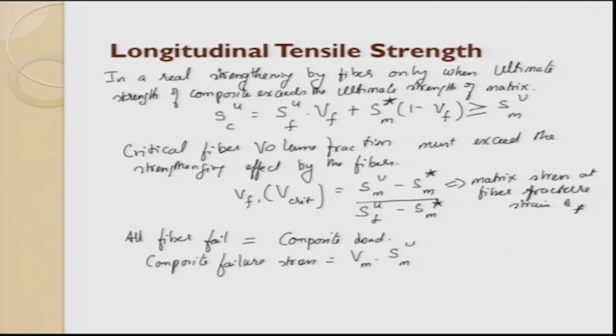So what happens is, if you see the strength versus volume fraction, there is something like a graph like this. So you are supposed to find out this point where you get the best benefit out of adding the volume fraction to the composite, so that you get a very good strength. So what we are trying to do is find out this V min. Why is this V min? Adding more than this reinforcement does not play any major role.